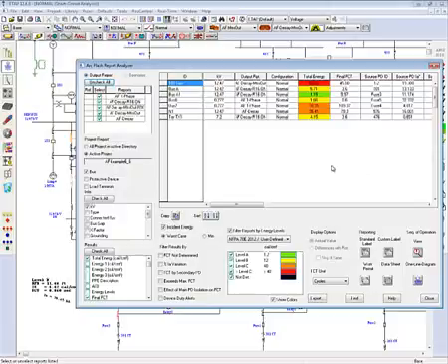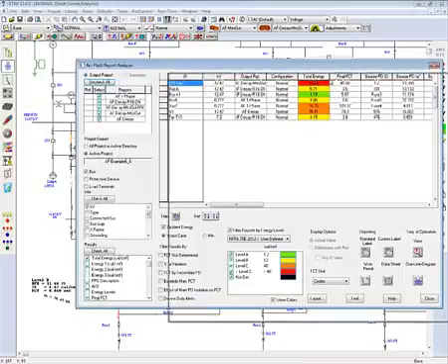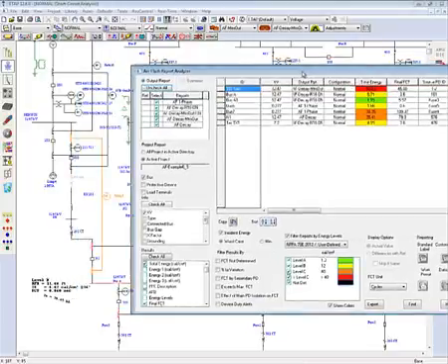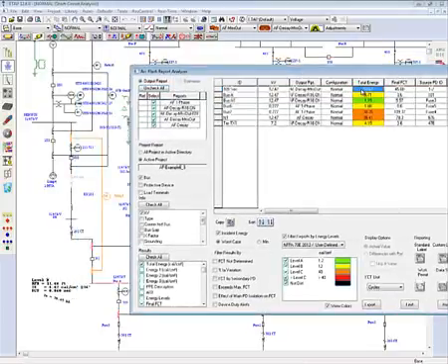I have here configured my Arc Flash Report Analyzer to show my incident energy worst case for my NFPA 70E-2012. And I'm going to go ahead and launch the sequence of operation for my 101 secondary and figure out why my fault clearing time is at 45 cycles and an energy of 50.63 cal per centimeter squared.